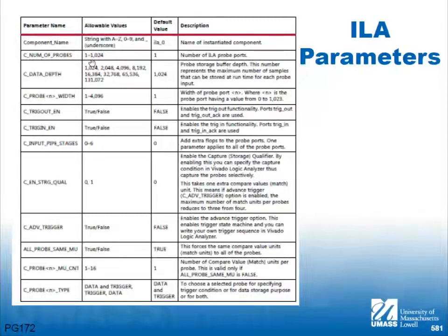I can tell you, if you're using 1,000 probes and 128K of depth, ain't gonna work. Right? You're gonna fill up all the memory. You're gonna run out of block RAM. I have had cases where I had a chip that used a lot of memory, and because it used a lot of memory, it had difficulty fitting the logic analysis in it. So what I did is I made changes to the chip for debug that would reduce the amount of memory that it used so I could fit more logic analysis in it. Did my debug, bring up all things I had to do, and then I went back to the full memory version of the chip and took the logic analyzer out.